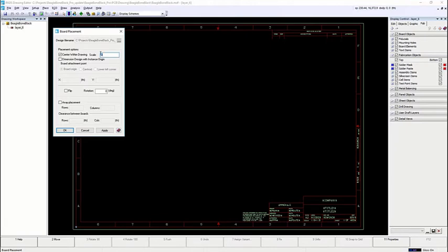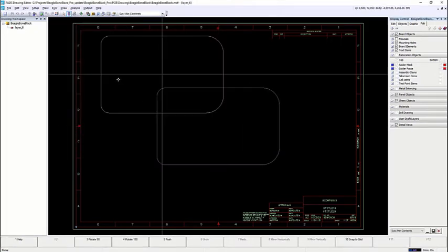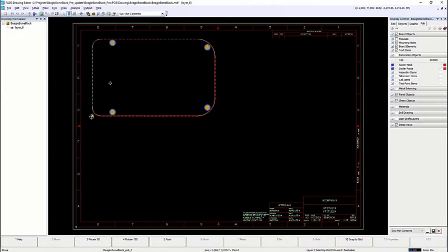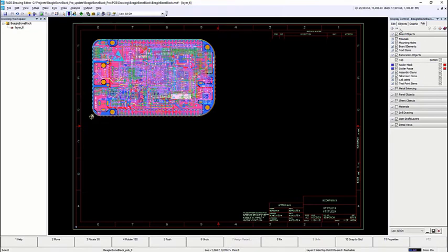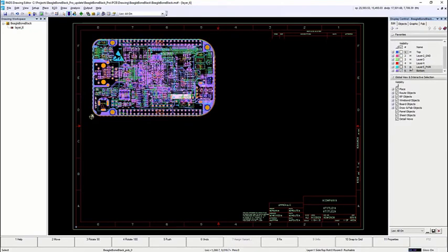You can create multiple sheet drawing files such as assembly or fabrication drawings that incorporate the PCB design. With ease, add a sheet with important information to keep for your own records and to send to applicable parties. Here, we'll create a sheet with information regarding layer 6 of this design. In this sheet, we can add a layout image of specifically layer 6's vias, routes, components, rule areas, and more.